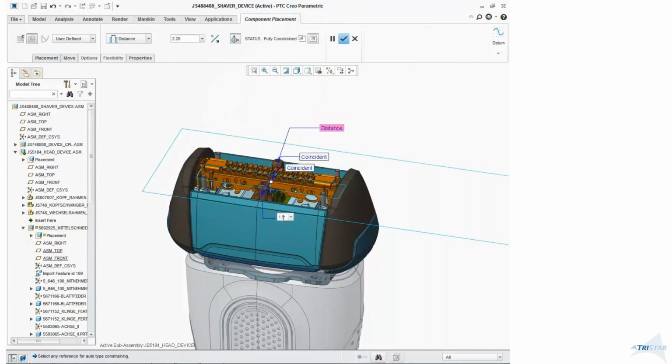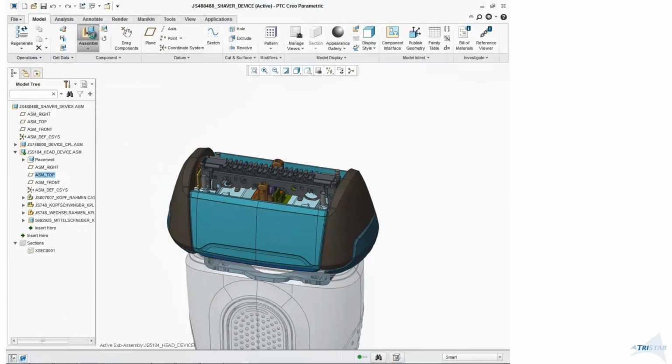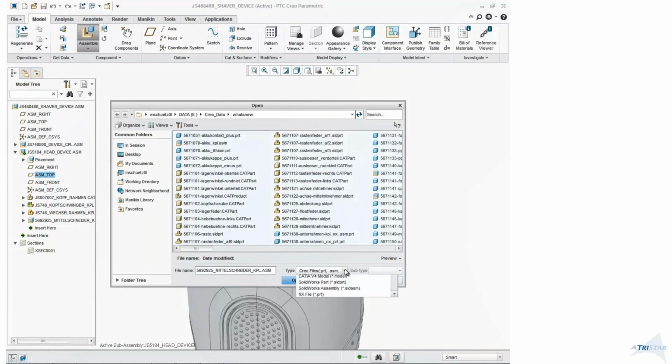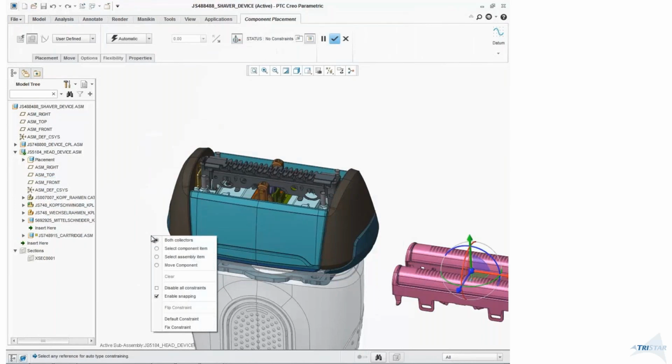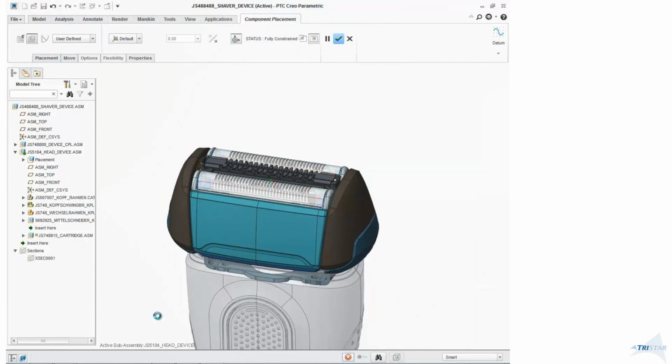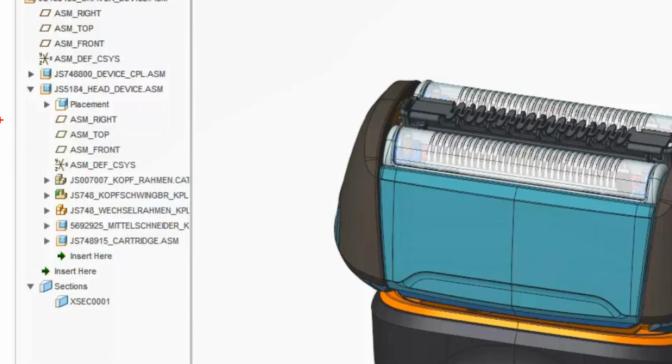So that's what I'm doing right now, where I've picked a couple of geometries within that subassembly. And if you want to maintain your design intent better, I would encourage using skeletons too. But here I'm assembling the cartridge subassembly here, which is a Creo subassembly that I've assembled. So if you look at my final assembly or the subassembly there, if I could just zoom in here, there is my Creo top level assembly, and then there is a subassembly, a couple of subassemblies in there.